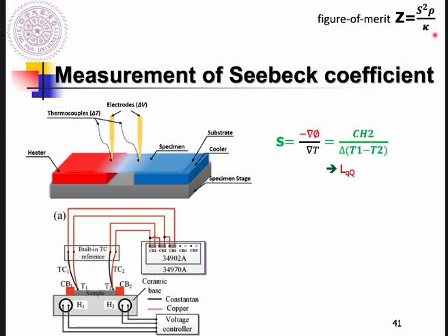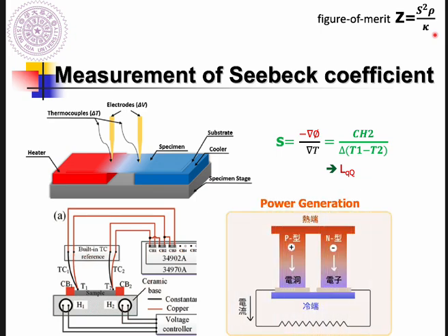And I want to give you an example here, where people use thermoelectrical materials as a power generator, which means that this device serves as a battery. Because this is a battery, it provides a current passing through this resistance. So don't forget, this is a battery. But here you see that we do have two materials. The first one is P-type and the other is N-type, and we have a hotter side on top and a cooler side at the bottom, to create a temperature difference.